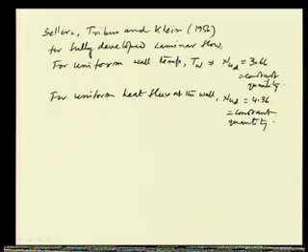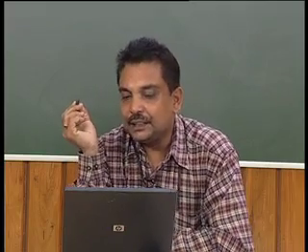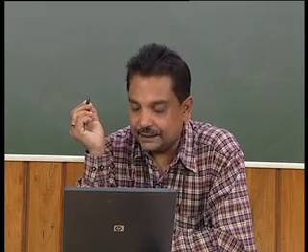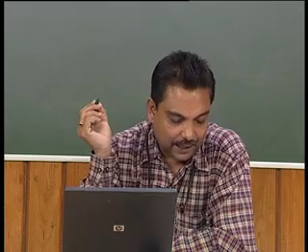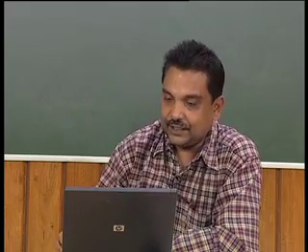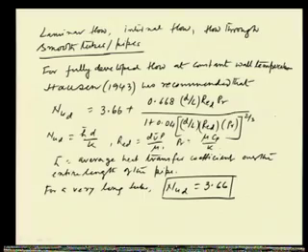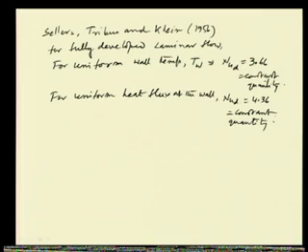So, we can see that when there is a uniform wall temperature, then the Nusselt number is 3.66 when the length is very high, but Hausen has given some extended form of that. So, it has generalized this, and when L is very high, then it is becoming 3.66.